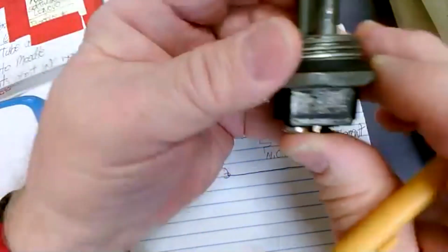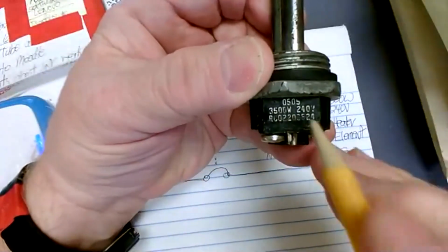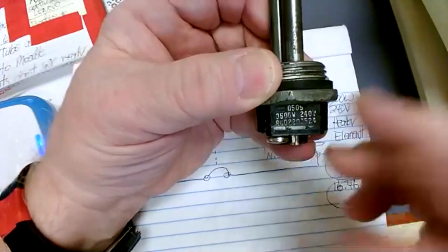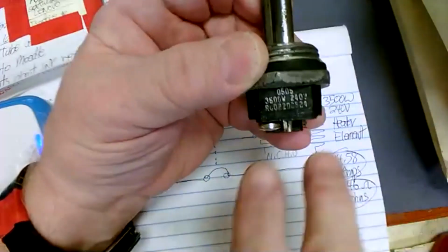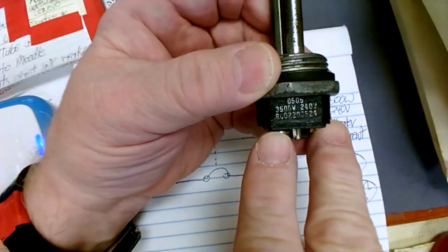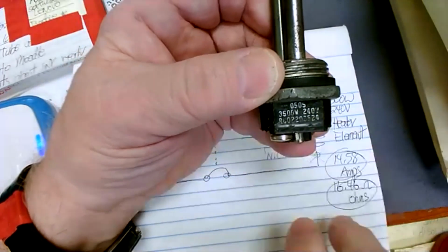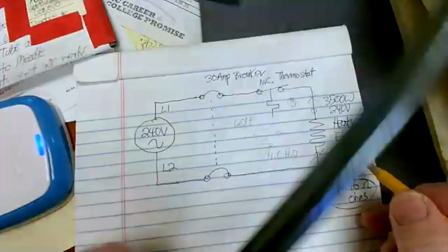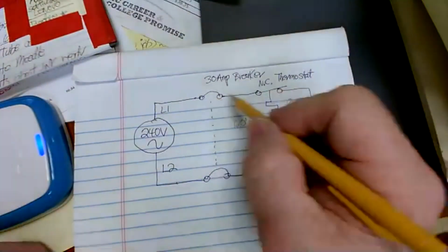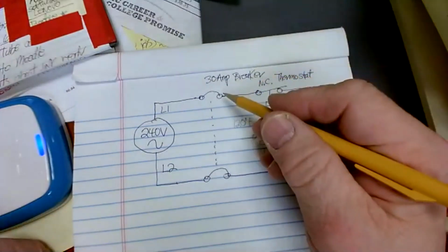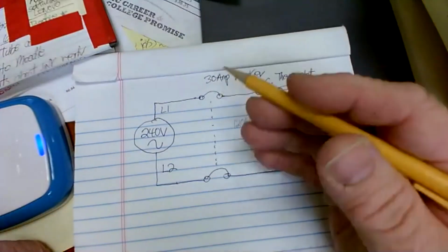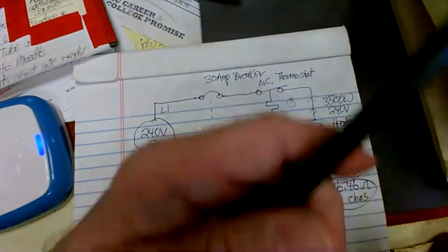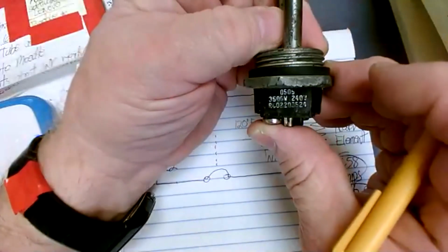And again, make sure that the ratings are the same. You don't want to vary. You don't want to go lower. Don't want to go higher, okay? If you go higher, your wire size might not be big enough, and you can have a fire hazard. If you go to a much higher wattage, here's what's going to happen. It's going to try to draw more amps than that. Your wire size and breaker size are not going to be able to handle that, so it'll probably end up tripping the breaker if you exceed this.